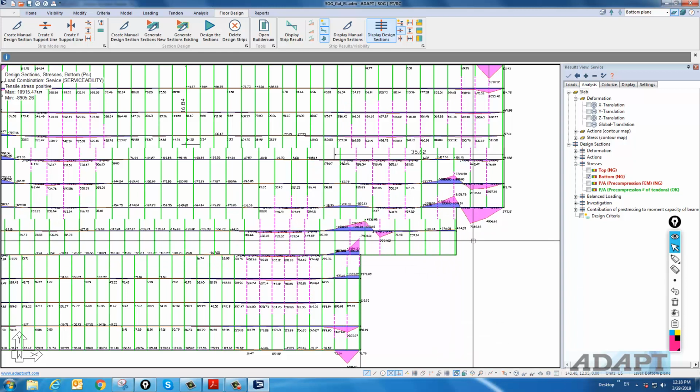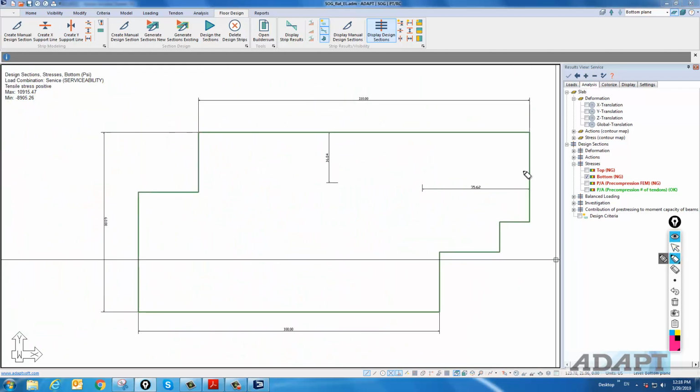So to relieve that type of condition, what we would recommend the user do is take these edge displacements and pull them off the corner. Let's say that we pull these off by 2 feet. I put them from point of the edge to point of the edge, but we'll pull them all off by 2 feet. So we leave a gap that allows the slab to be unrestrained at that position. And I would, again, take all of these and just model them with a 2-foot offset like so. And this is where we would pull those back to.